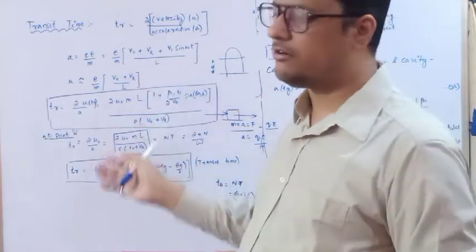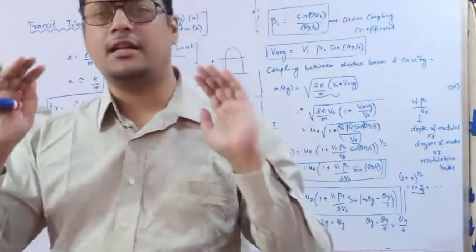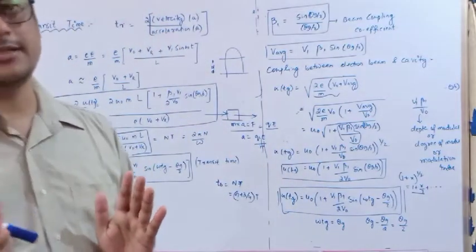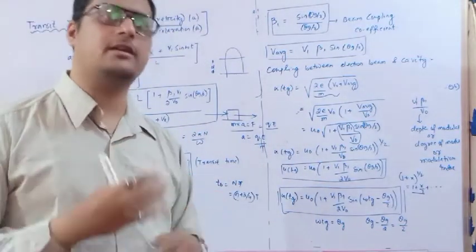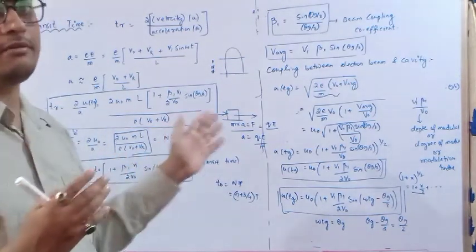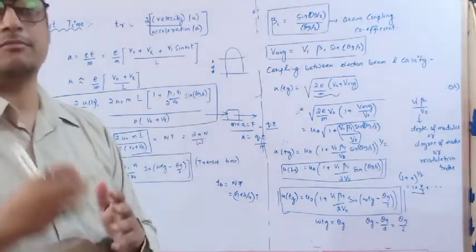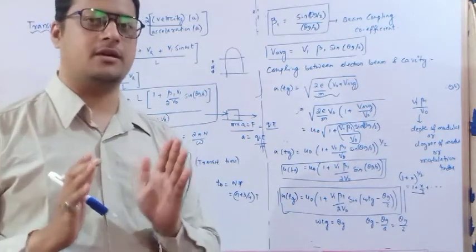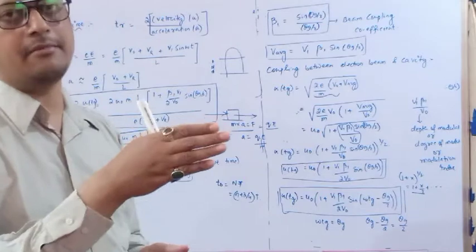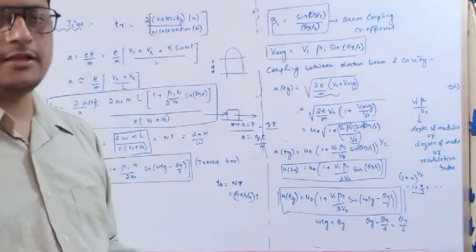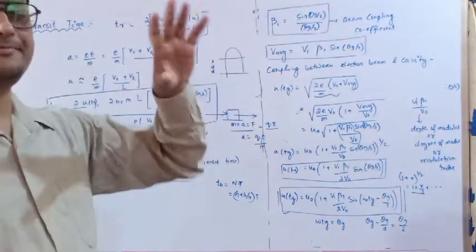Velocity modulation means that when the electrons cross the particular gap, on entering the gap the velocity automatically changes. With the help of this relation you can understand: before the gap it only has the DC beam voltage, but when it enters the gap, the RF potential is added to it. Then what happens?